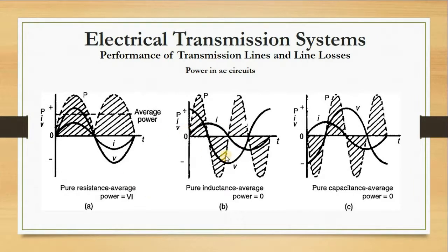First of all, what brings about this lead and lag in the inductive circuit? The inductor is basically a coil, and a very thin one may be called a choke, but basically it's a coil. The behavior of the inductor is that it only reacts to changes in current. So long as there's no change in current, it's not going to react to it.